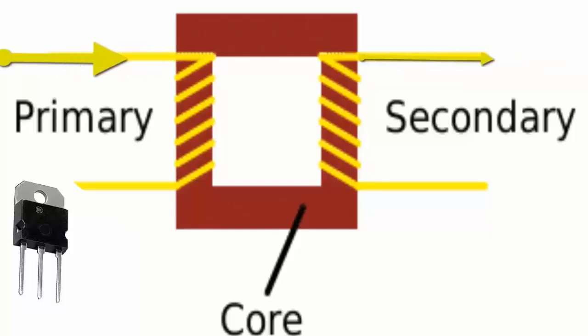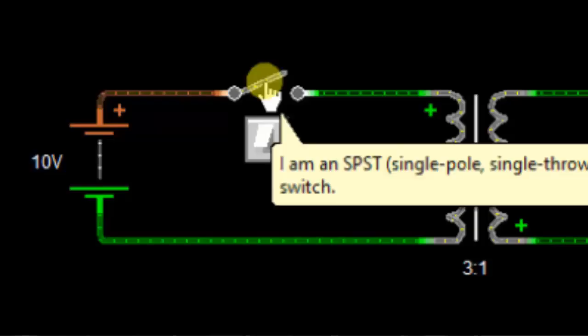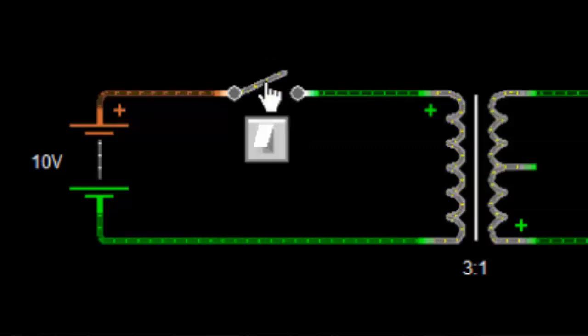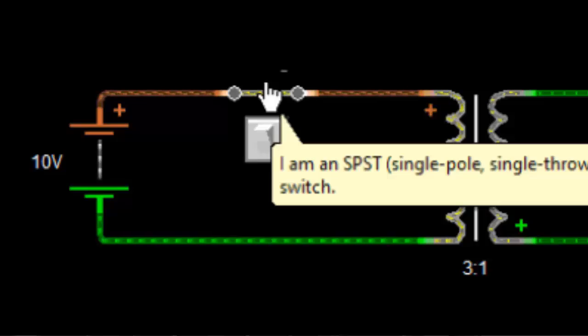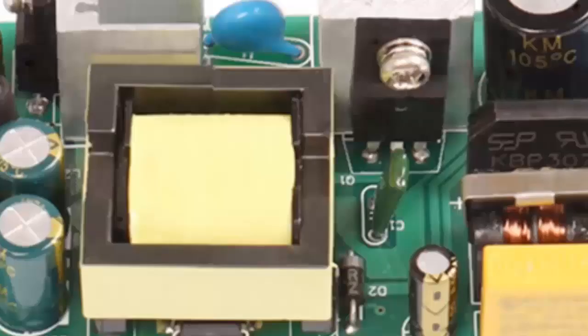2. Switch mode transformers, also known as switching transformers, or high-frequency transformers. Unlike conventional transformers, switch mode transformers do not directly receive current from the external electrical network, but receive it from a special current generated by the electronic board, which operates at high frequency, usually in the kilohertz or megahertz range.